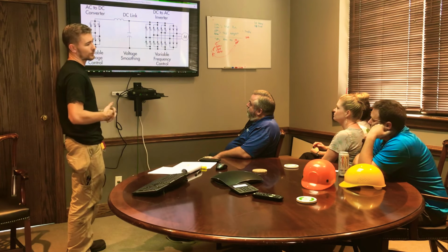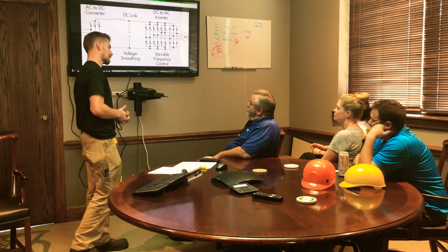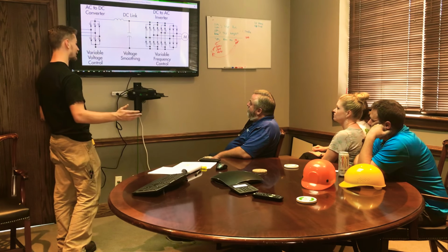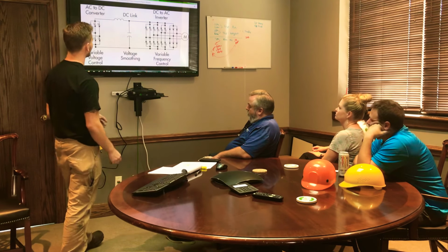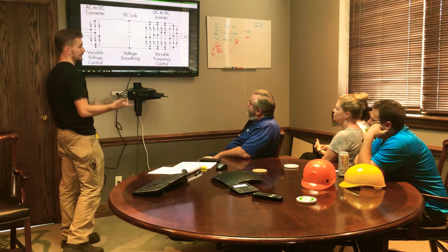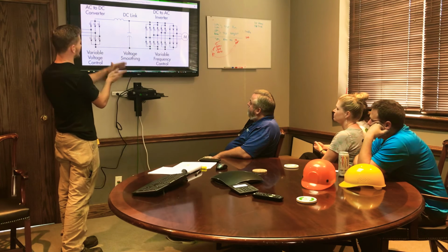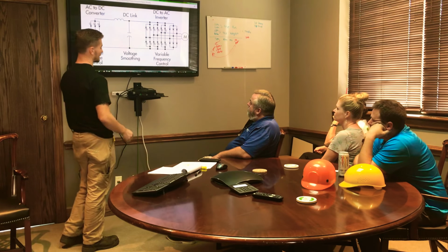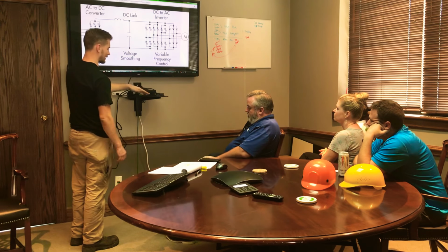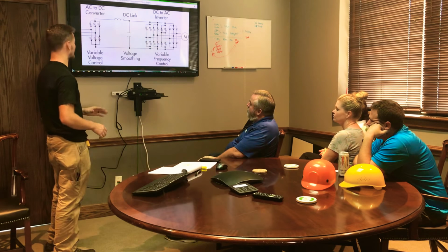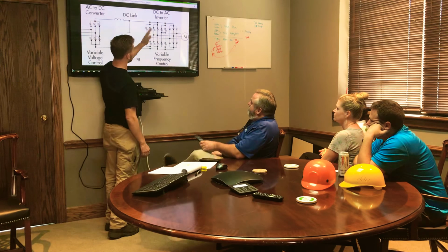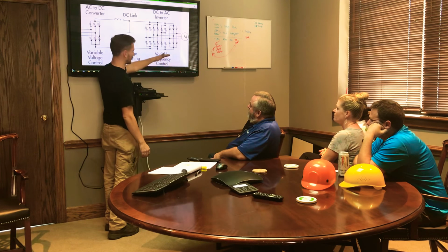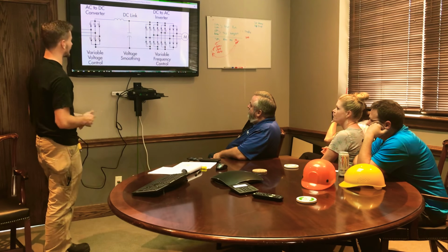The next and last component within a VFD is the DC to AC inverter. What that does is it outputs that direct current back out to alternating current at the frequency that the VFD desires. The way it does that is switches, we'll call them switches, they're actually transistors wired into two diodes, and these switches choose whether to output positive voltage or negative voltage. So let's say it wants to output 1 hertz, which we remember is 1 positive 60 volts to 1 negative 60 volts in a second. Well, they'll all switch over on one phase. They'll output a high for half a second, and then they'll all switch over and output a low for half a second, right? Which will give you 1 hertz of alternating current output to the motor.